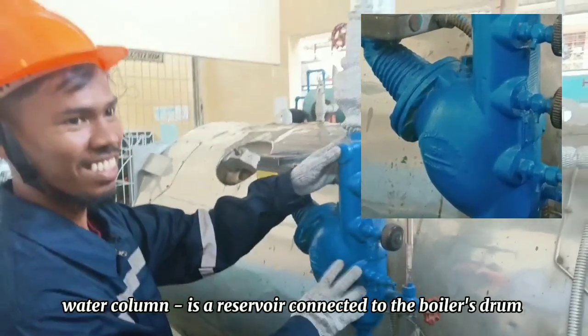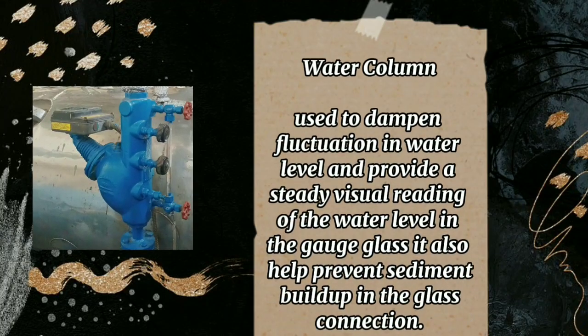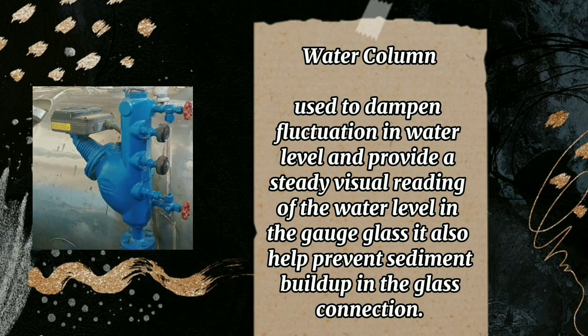A water column is a reservoir connected to the boiler's drum, used to dampen fluctuation in water level and provide a steady visual reading of the water level in the gauge glass. It also helps prevent sediment build-up in the glass connection.